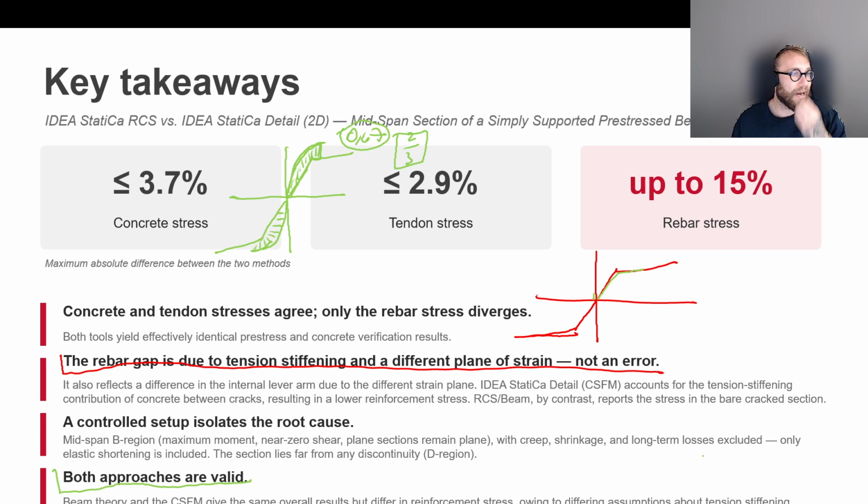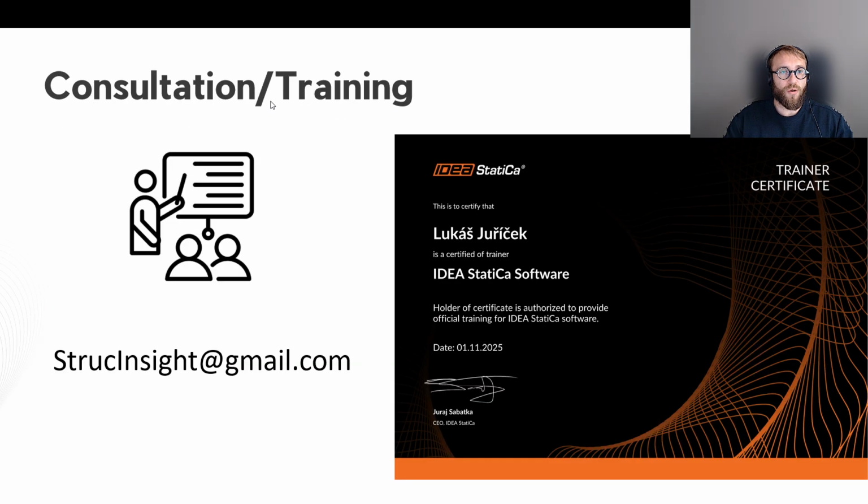So I would say the high-level approach for 2D detail brings a lower level of stresses on the reinforcement rebars, because some of the tensile stresses are consumed by the portion of the tension that is at this area and is applied on the reinforcement bars.